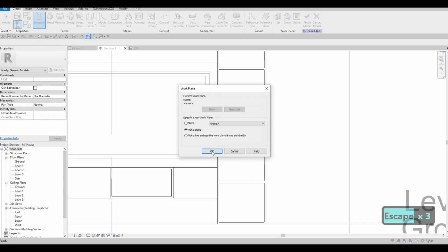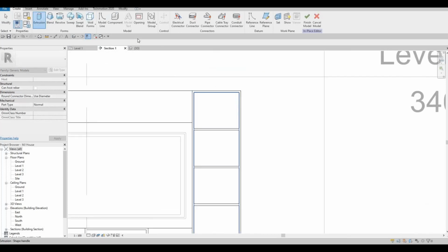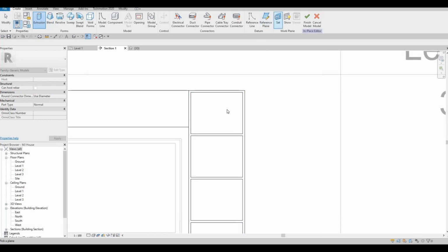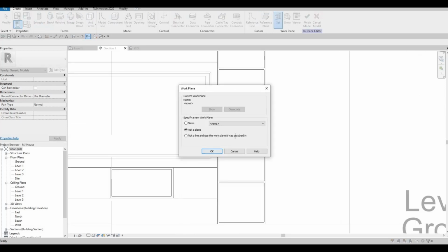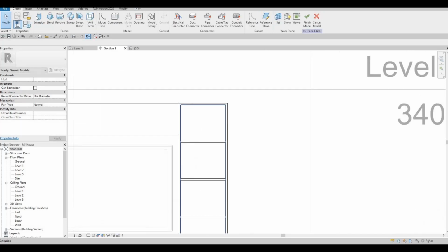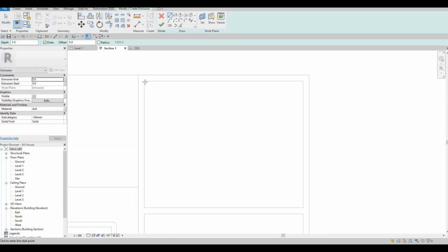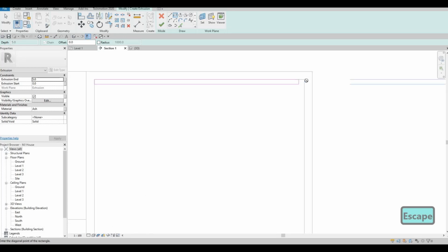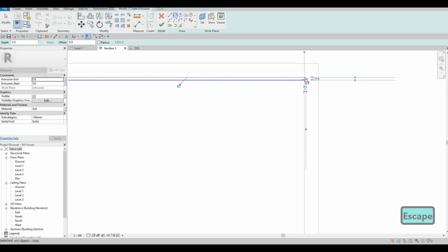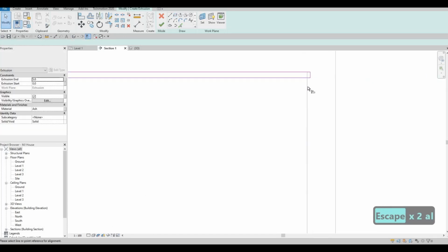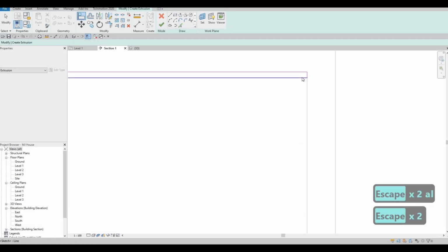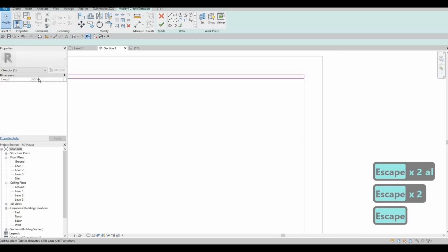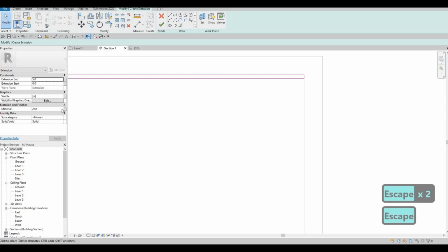And then now let's do an extrusion again, but with that backing right there. So I'm gonna select, set this one, pick a plane, select that, and then another extrusion similar to what we did, make it rectangle, and then align it right here. And then this one is 5, and then this is 5.